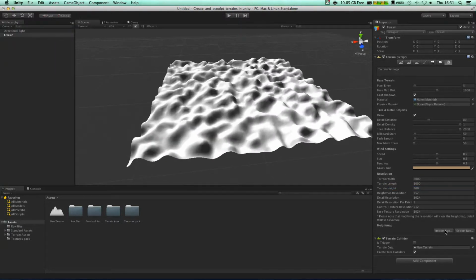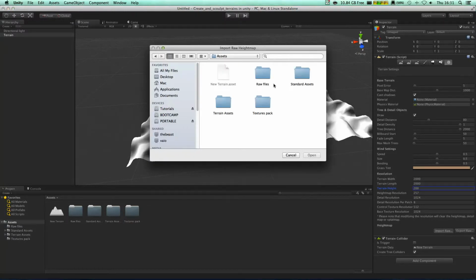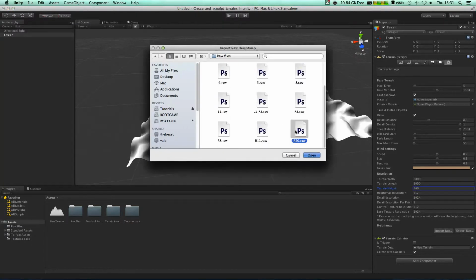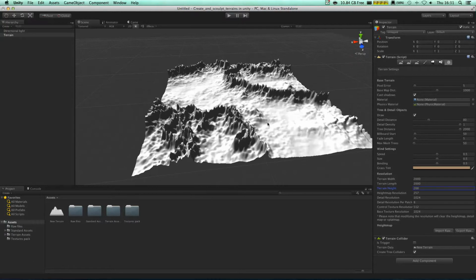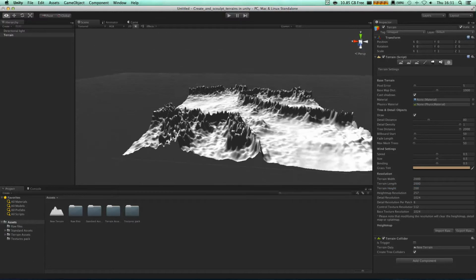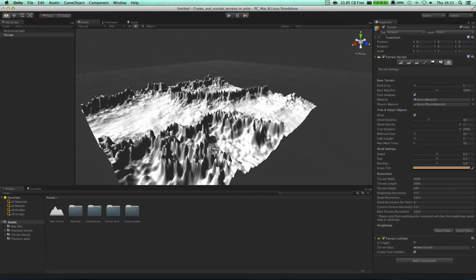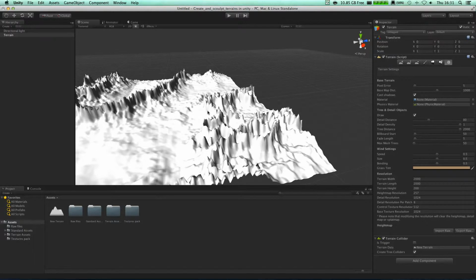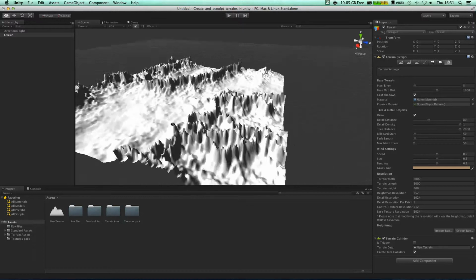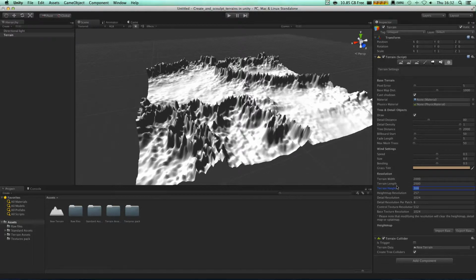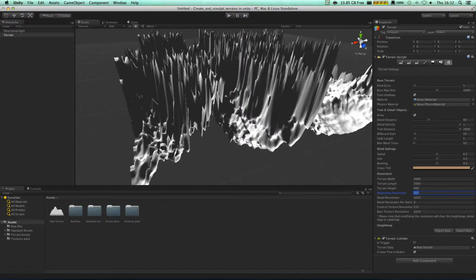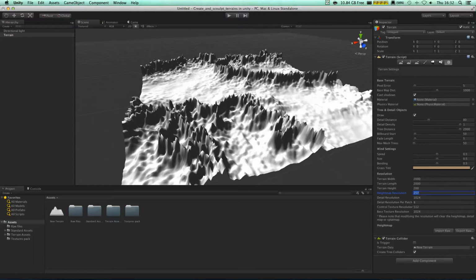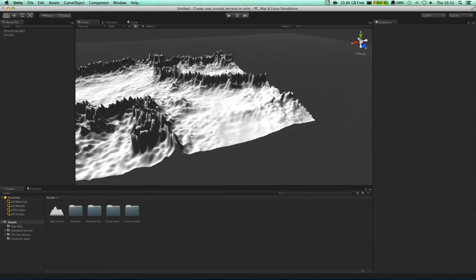In some of the other ones, you can see over here, I'm gonna choose this one maybe. In some of the other ones, you're gonna have weird things coming because Unity cannot really recognize the last kind of wide values, and if you have, for example, 600, it's gonna come out like this. So in order to prevent this, it's better if you go with 200 and later smooth out those parts.